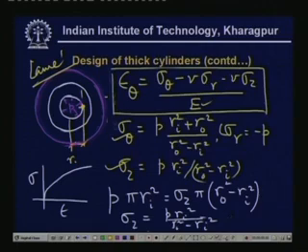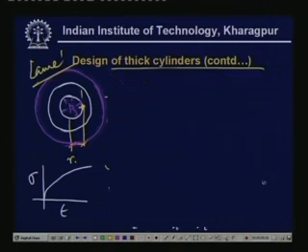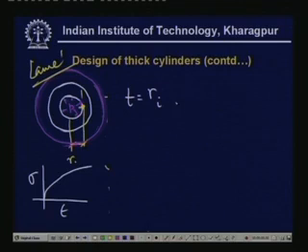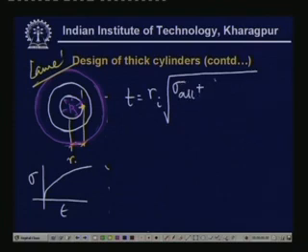that is, T will be equal to Ri times under root of sigma allowable plus (1 minus 2 nu) times P divided by sigma allowable minus (1 plus nu) times P, minus 1. Earlier it was 1 minus nu, now this is 1 minus 2 nu.